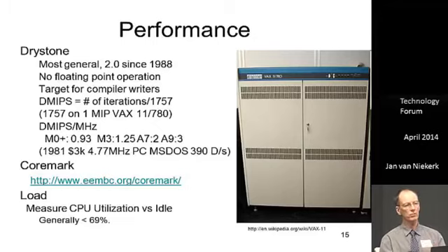So the real point is, one of the very simple things that you can do is to download the Dhrystone, compile it and run it, or download the CoreMark test, compile it and run it. But the good news is if you just Google a little further, you'll find 4 or 5 sites where somebody with some extra time has essentially benchmarked every controller, and ARM themselves publish a bunch of this.